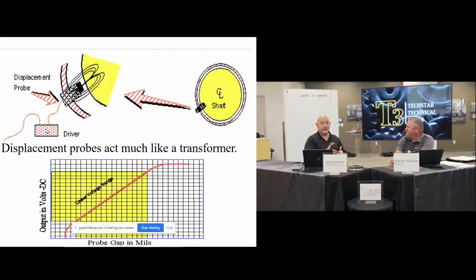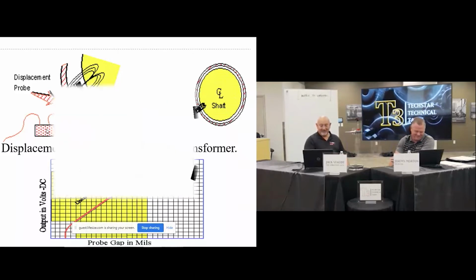They try to take out all the scratches. If you have a scratch in that area, your probe is going to look at that when your machine is running, and it's going to help amplify your amplitude. You just created a keyway for a phase reference. That's right. But yeah, I've seen people take a knife and cut that tape off. Absolutely. You've got a clean knife stroke across that burnished area. Yeah, you don't want to use that. Don't do that. Yeah, that's correct.